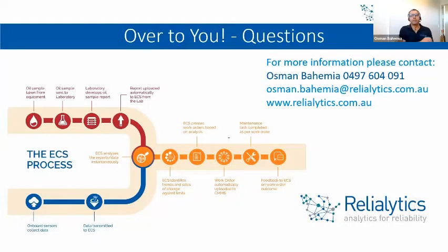A question that came through overnight is about extending component life by supplying clean oil. Is it okay to set the cleanliness level for new oil lubricant delivered on site? Angus or Matt, do you want to take that one? Yeah, look, I could probably field that one, Matt. Absolutely critical to understand the cleanliness of the oil going into your equipment. If you're starting off with contaminated oil, then you're basically fighting an uphill battle. So absolutely specify limits for cleanliness.